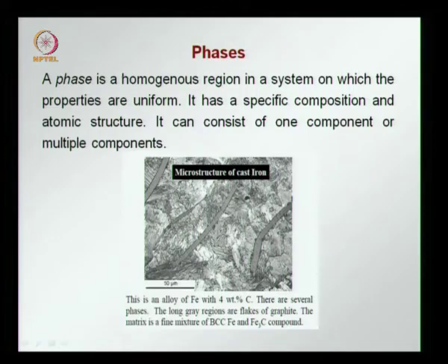So, the aggregates form one phase and the hydrated cement paste forms another phase. In cast iron, the phases form as solidification occurs from the melt. Since the quantity of carbon is very high, this forms a separate phase of graphite within the cast iron.